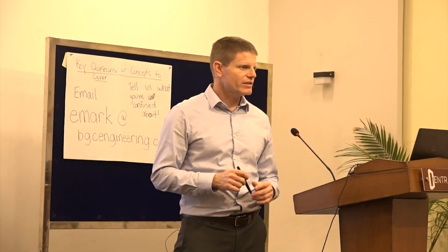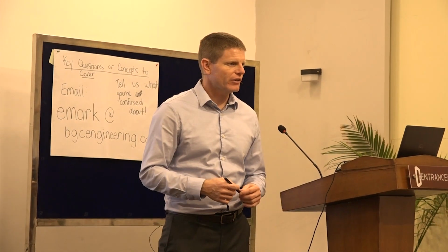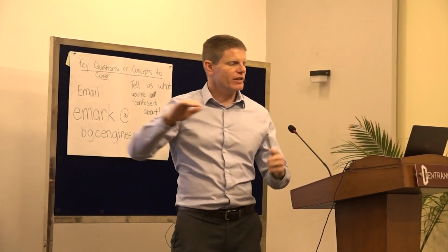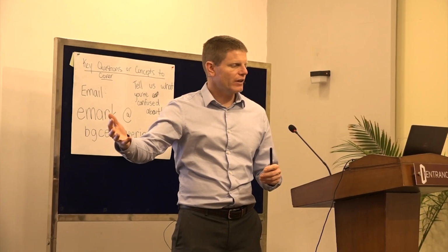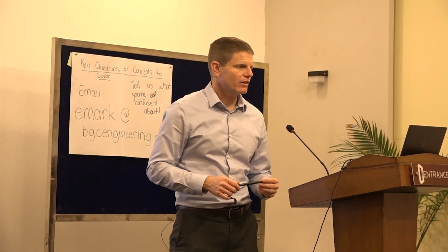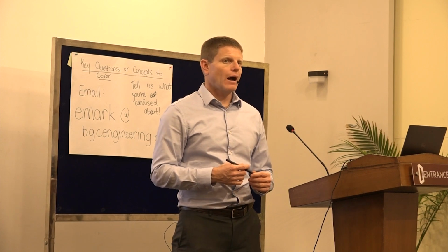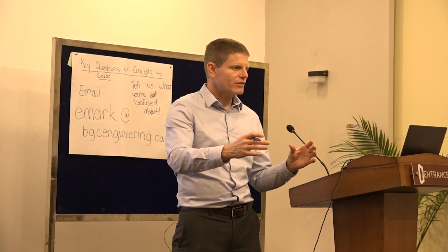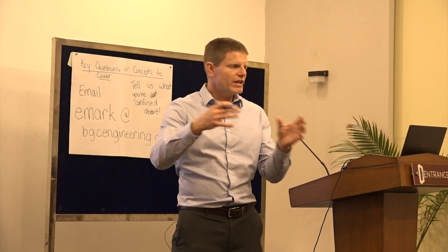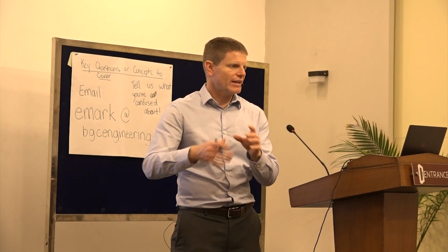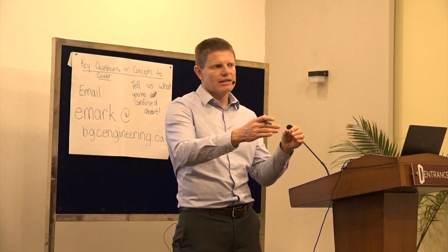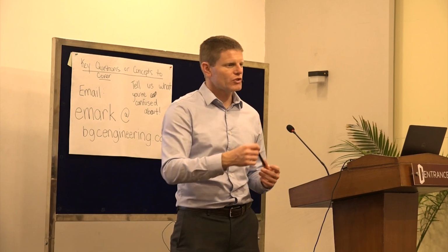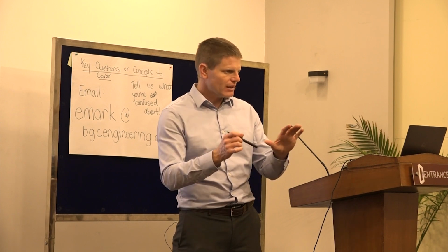What I was trying to say is there is still a probability of failure. And so this method that we just described is an alternative way of looking at failure that has nothing to do with the safety factor. So even if you do a calculation that shows an adequate safety factor, there's still ways for the structure to fail. You can't say that because the factor of safety is adequate that the dam is entirely safe. That's the point that I was trying to make. Is that clear? Okay.